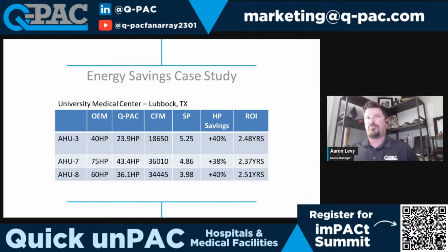Once that system was put in, it's probably even higher, depending on their demand level. So a lot of times when we're talking about ROIs for these particular systems, what I would consider standard HVAC is between about 2 inches of static and maybe less than 6, 5.5, somewhere in that ballpark range. That's the bread and butter of these fans, like efficiency standards, right in that window. And a lot of those will give you ROIs as low as 12 to 48 months, depending on operating hours, run times, things like that.